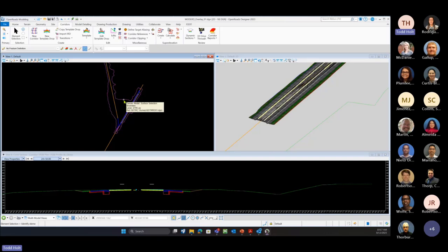With Wakulla, we had additional survey come in over in this area. So we want to edit Wakulla, and we want to take out the delta terrain and add in the new additional survey. That way the name of the terrain model stays the same, but we can exchange out information for that project. That would be another option that you could do.